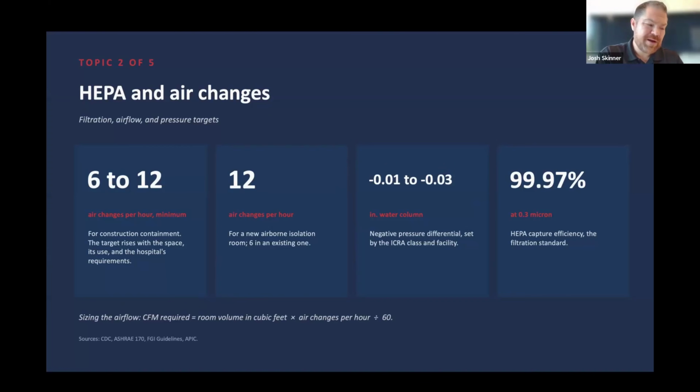I think there's a couple things there. And if we take it back to the start, Robert touched on it earlier. One, do you have the right HEPA filter? So at least 99.97 efficiency, bare minimum. And we're seeing more and more hospitals moving up to giving themselves 99.99 as the minimum requirement. And the reason there is it gives you more coverage, cleaner air, etc. So that's piece number one.